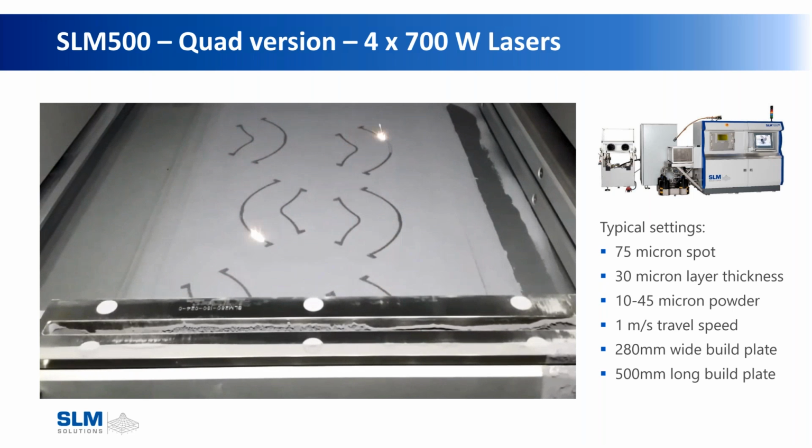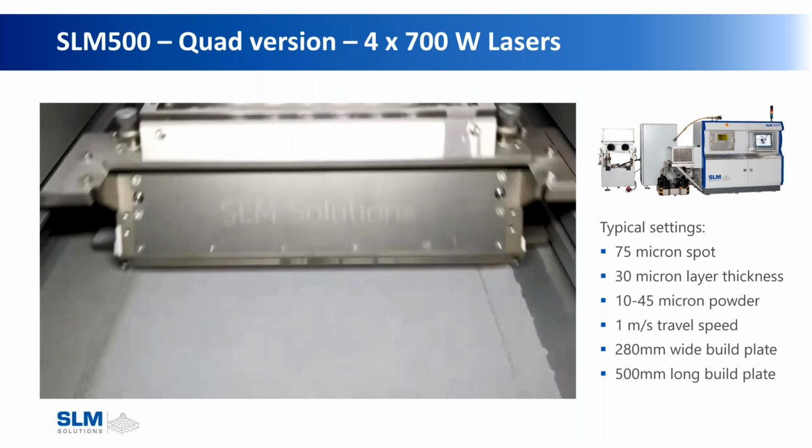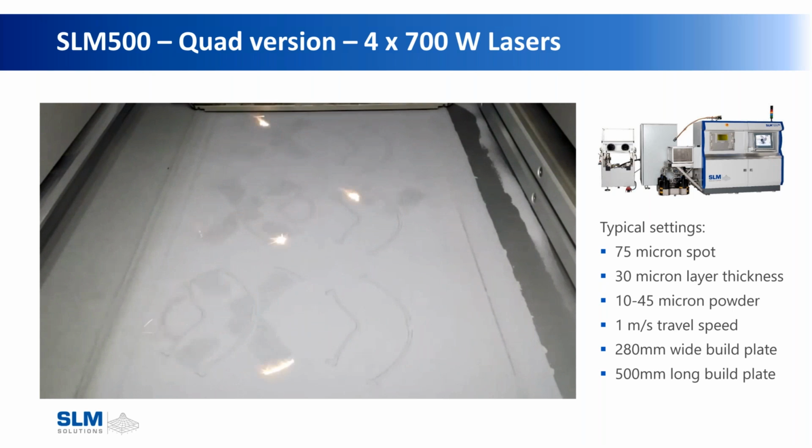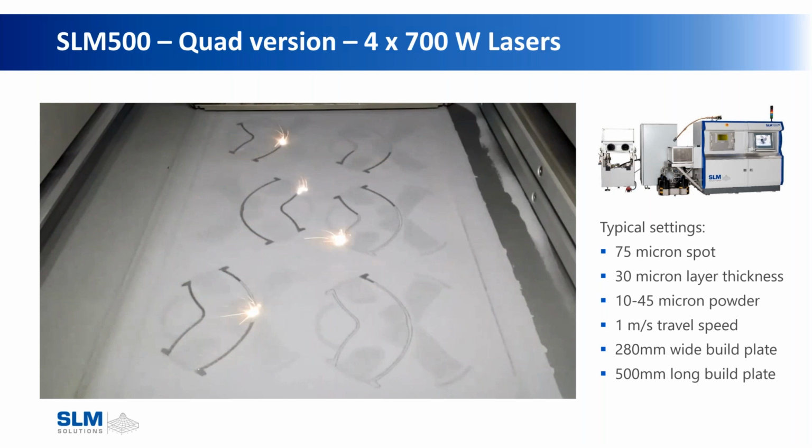So the typical machine, metal additive, you're working at 75 micron spot size and an average of 30 micron layer thickness. Now the layer thickness is dependent on what you're looking for. So there's 30, 60, and then for reactive materials, 90 micron layer thickness. For the 30 and 60, 30 is high quality, high resolution, slower build speed. 60 is a good balance between high resolution and high speed while good quality.